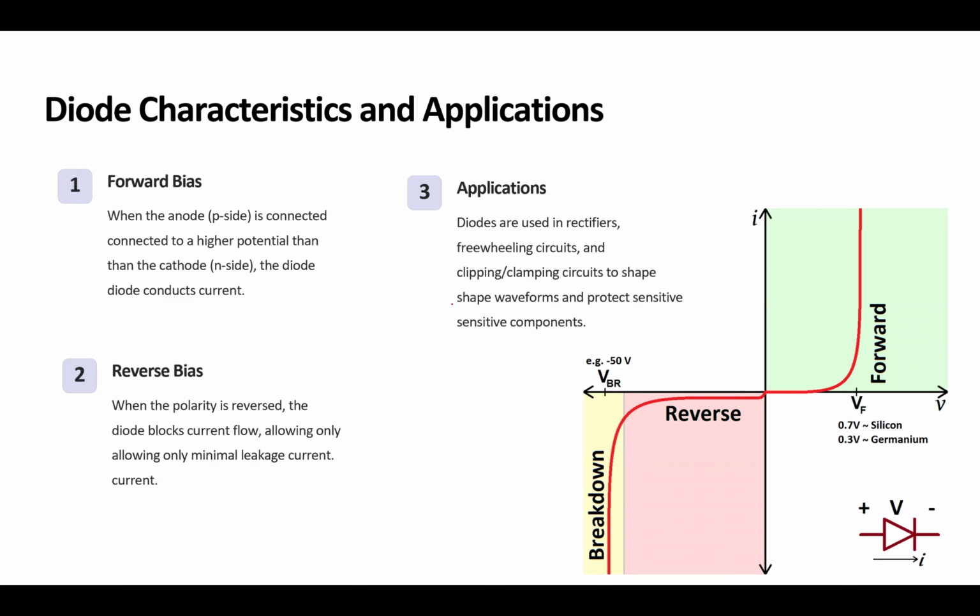So we are going to go through the hardware. What that means when you want to choose between the two: if you need a diode that turns on faster and is more sensitive to the forward voltage, germanium is the choice that you have to make. You see what I'm saying? So this is the type of mindset that you have to have.